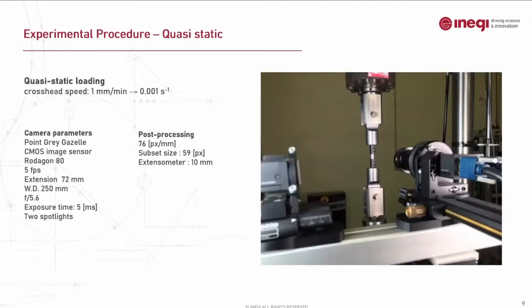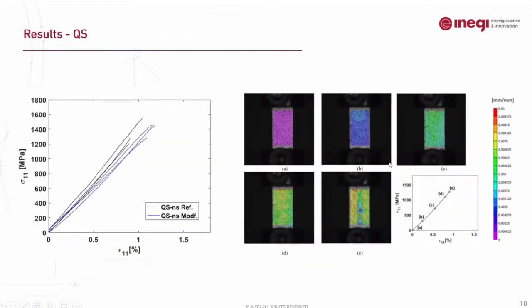At the same time, in order to study the rate dependency, we performed the same exact experiment, monitoring with a CCD camera to obtain the DIC images, and performed it in an MTS servo-hydraulic load frame in order to characterize it under the low strain rate regime. And here you can see the static result and the DIC map of the specimen.